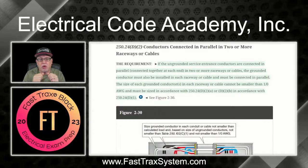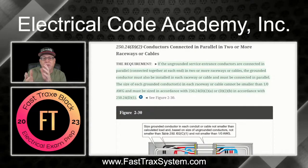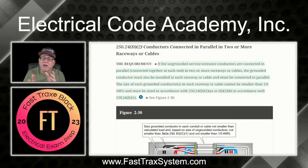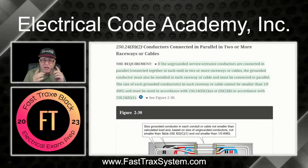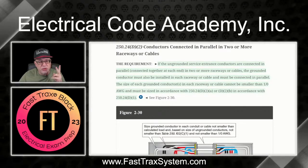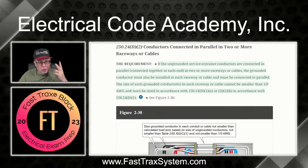Okay, and so this is a case where I'm going to be running multiple sets through multiple raceways, and I'm going to have a grounded conductor in each one of those raceways. How do I size that grounded conductor for that application? All right, so let's dig into it. So here's what we're looking at, 250.24(D)(2). Got your code book. Look at that. And again, parallels, 2 or more.